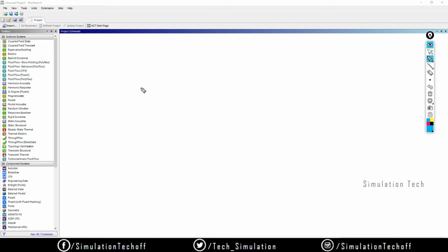So in the entire session we only use Fluent Flow, Fluent. Okay, that is Ansys Fluent. I'll just drag and drop this Ansys Fluent over here. Once it is placed, you may be surprised there is no engineering data at all. We only have geometry, meshing, setup, solution, and results.